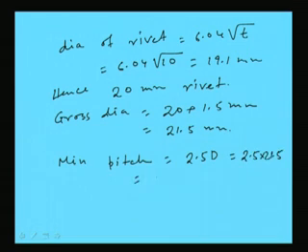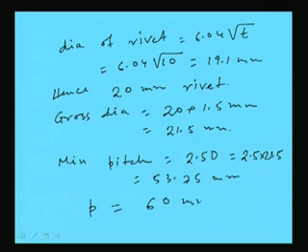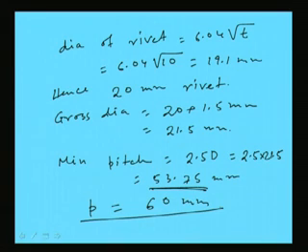So, this will become 53.75 mm. So, let us provide say pitch as 60 mm, because minimum pitch we have to provide is 53.75 mm and maximum is 32 T or 60 or 300, whichever is less. So, from this criteria let us provide pitch at 60 mm in this design.